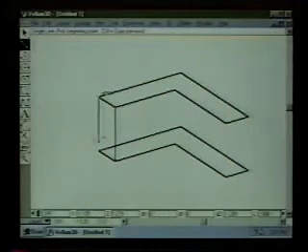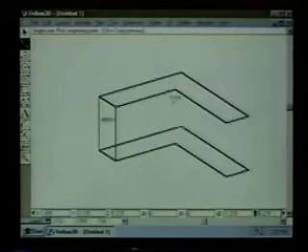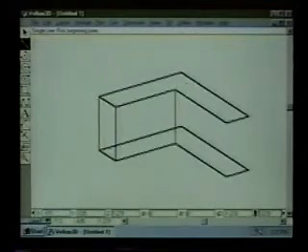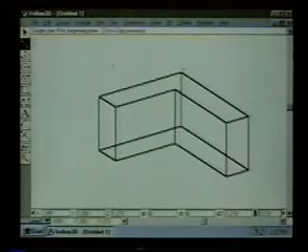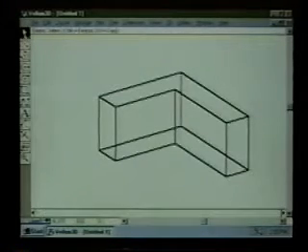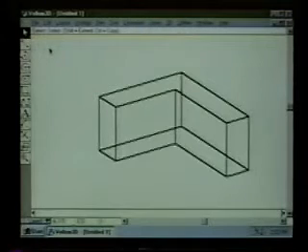I'm going to draw a line from here to here. Now actually I need that same exact line in all these other corners. Well, notice in the message line it says Control equals copy previous. So if I hold the Control key, then with one click I get the same exact line in all of these locations. And these are the type of little productivity enhancers that you find throughout Vellum.